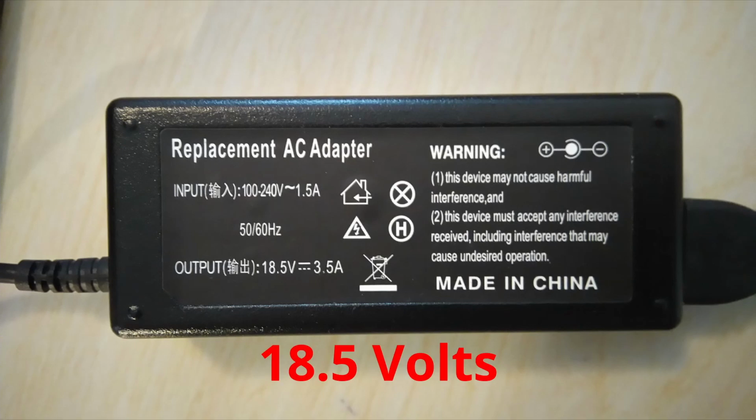That means this charger here does the job of collecting AC, 100 to 240 volts, and converts it inside this adapter and supplies 19 volts DC. The 19 volts is not AC, the 19 volts is what? DC. That 19 volts is exactly what the laptop needs to function, and it is DC current.